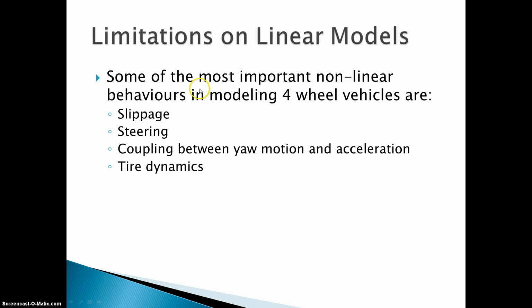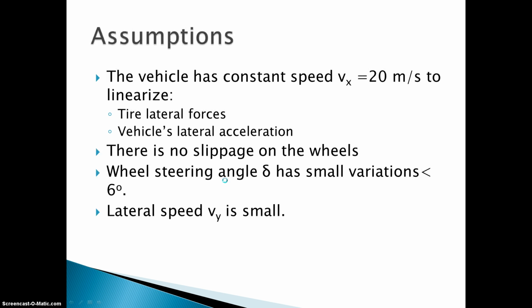There are some nonlinearities in our system, but we need to take care of these nonlinearities because we are going with linear control techniques. We know we have slippage, steering, coupling between yaw motion and acceleration, and tire dynamics, which are all nonlinear in nature.